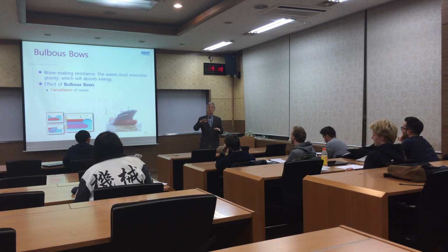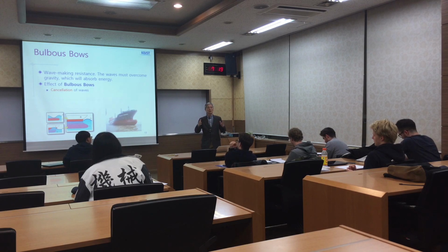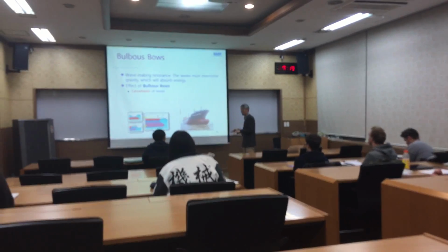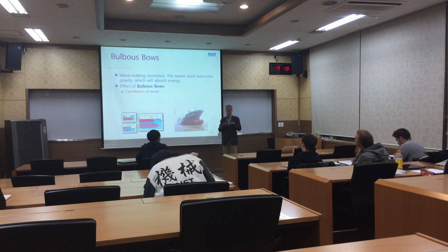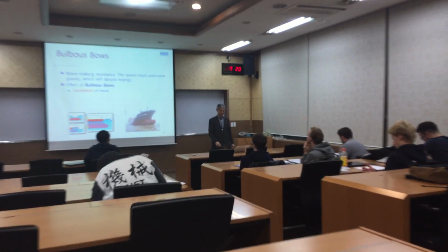But ship is changing their draft and pitch and trim and conditions are changing, right? So it's not easy to make such ideal condition. Usually you can have a perfect full draft design condition, so that can be the design point for bulb design.